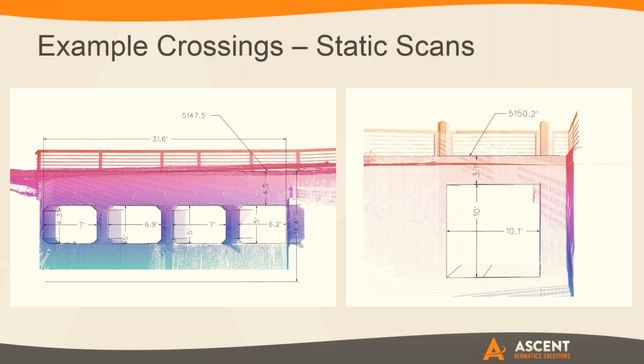Yeah, definitely in this example specifically, if you look at these culverts, these crossings here, you know that there's going to be sediment in there. So one thing that never really gets accounted for in a conventional survey is the sediment itself. How does that affect the friction and the way that the water moves? We can see that in there, especially in areas that have had flood events and major events come through, where there's a lot of sediment, a lot of buildup. What does the flow look like now? You can get that detail because you can get low enough in there with, let's say, a static scanner to look in and see what it is doing underneath the bridge.